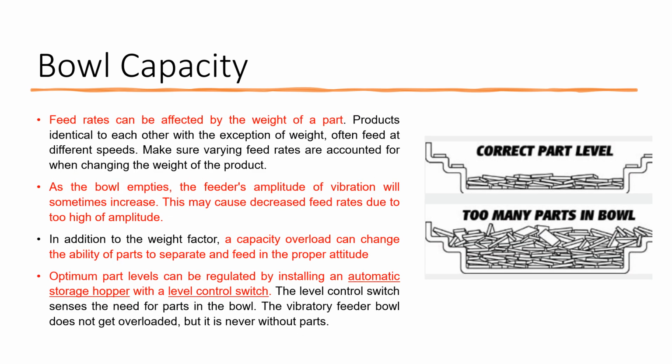Then the bowl capacity. Feed rates can be affected by the weight of the part. If the bowl is empty, the feeder's amplitude of vibration may sometimes increase, and that can cause a decrease in feed rates due to too high amplitude. Capacity overload can change the ability of the parts to separate and feed. That's why we always check the bowl capacity, whether we have too many parts in the bowl, or we are feeding the parts at proper levels.